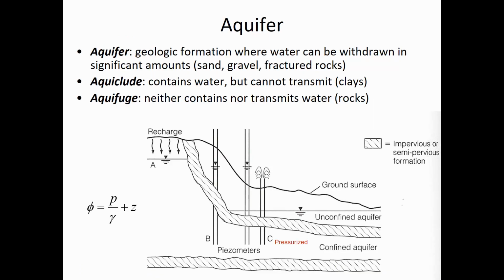Here's a cross-sectional view of an aquifer, and there's some terminology here that you need to be acquainted with. What we're looking at is actually a confined aquifer. And by confined, what we mean is that there's a layer underneath and a layer above the main body of soil that is saturated with water. And that layer up above can cause the water that's beneath to become pressurized.